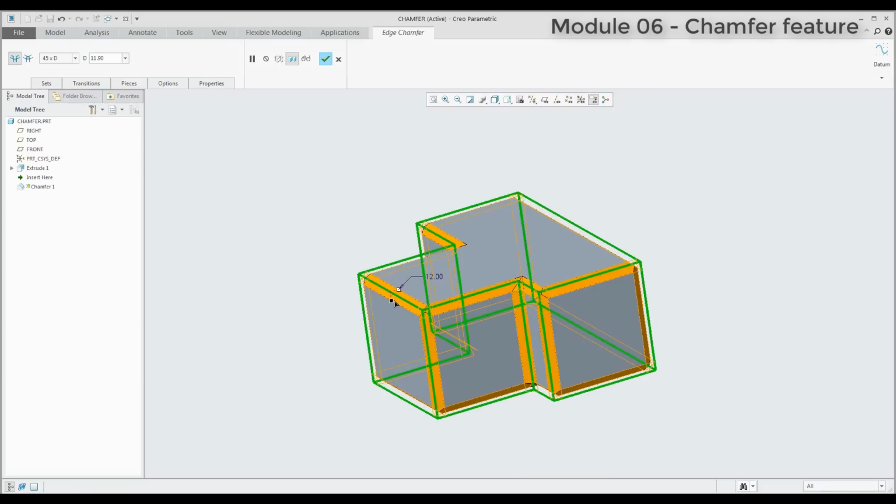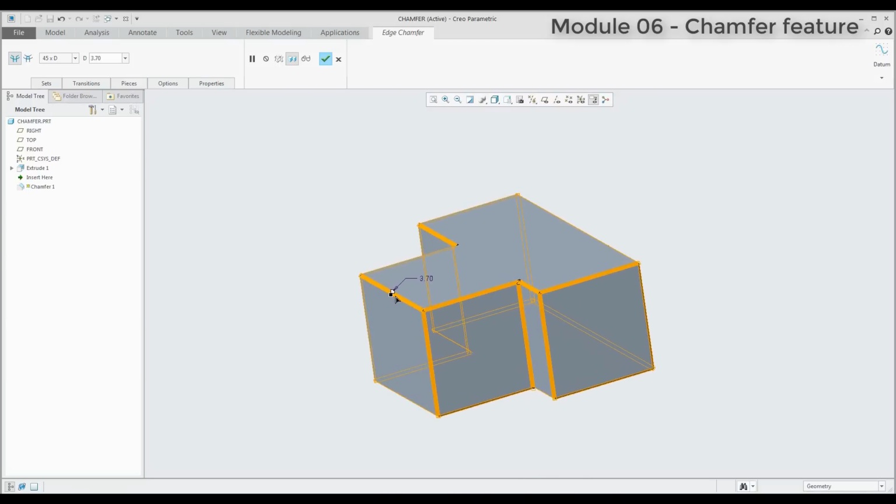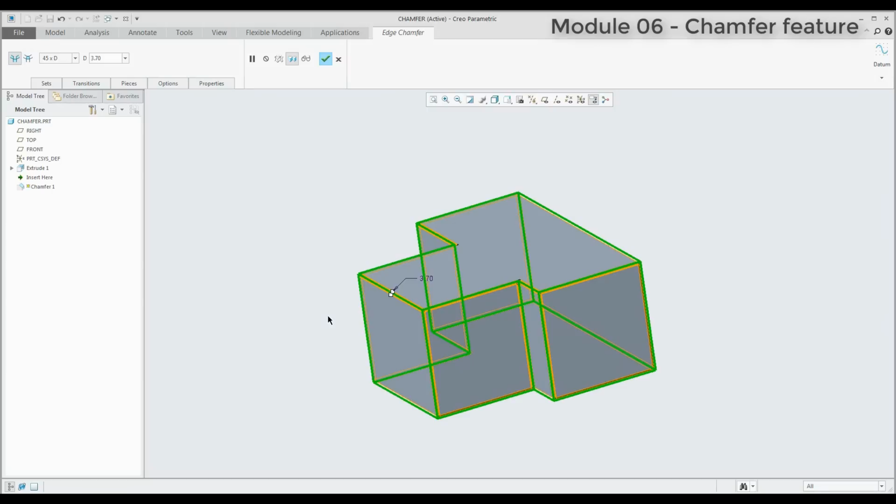And right now you can see that I quickly made the same chamfer for all edges on my 3D model. I know this shape is really easy, but I'd like to show you how the system selects the information from the menu. In the sets you can see the system will create three sets for me. In one set, three intent edges were selected: top one, bottom one, and vertical. You can delete or remove them if you need.